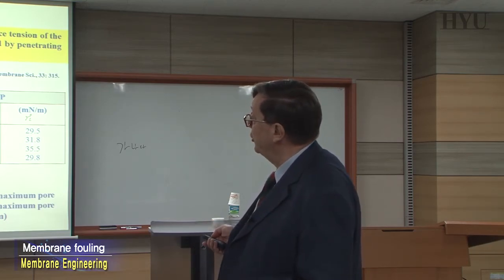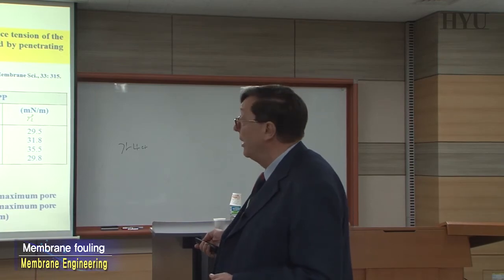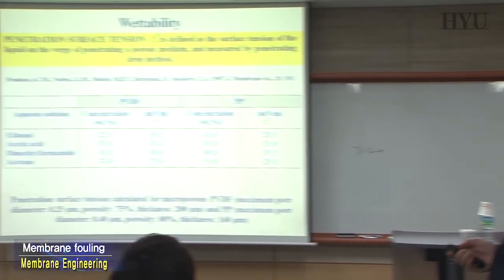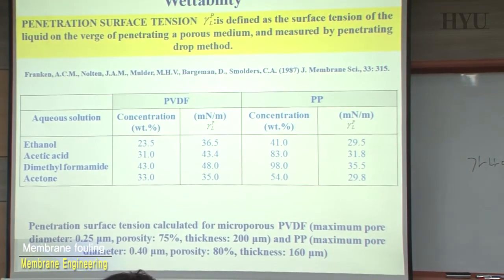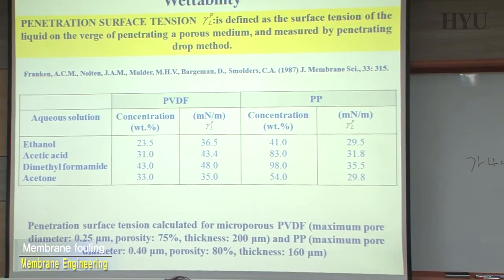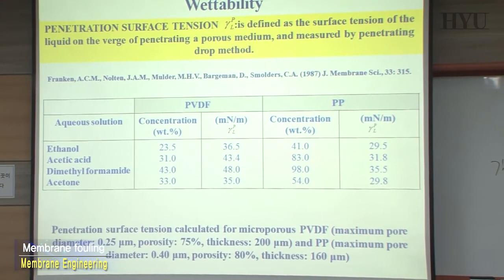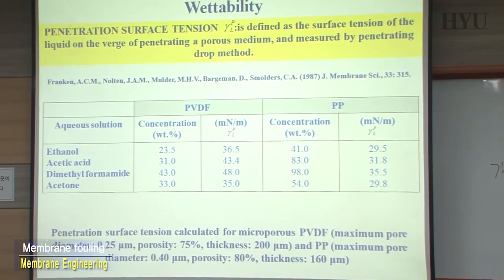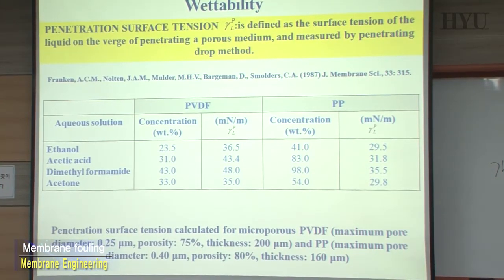Membrane distillation, we will learn, is very much related to the surface energy of our system and to the surface tension of the membranes you are using. For membrane distillation, we will learn you need hydrophobic membranes, not hydrophilic. If the membranes go from hydrophobic to hydrophilic, you block the system. Membrane distillation does not work anymore.